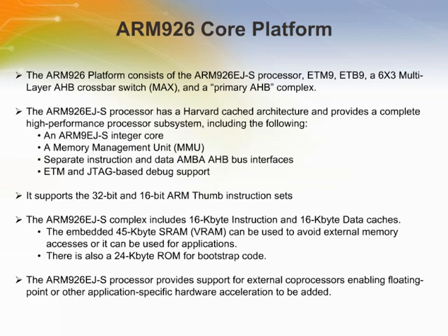The ARM926 supports the 32-bit ARM and 16-bit Thumb instruction sets. The ARM926 includes features for efficient execution of Java bytecodes. A JTAG port is provided to support the ARM debug architecture along with associated signals to support the ETM9 real-time trace module.